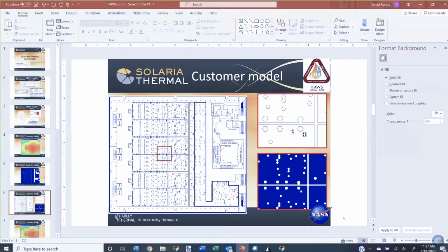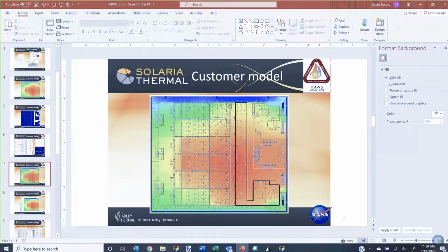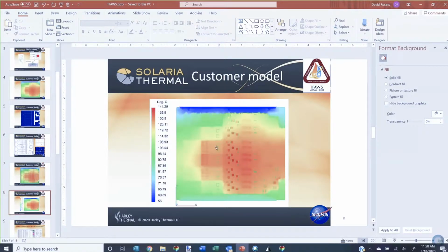And to get the heat from here to here, you've got to conduct across 25 mils of plastic. Okay, and because they're lined up, if the metal doesn't overlap on different layers, it's going to create this thermal resistance between here. Okay, if they shifted one of them or every other one by 100 mils or 200 mils, then you'd create a conductive path across it.